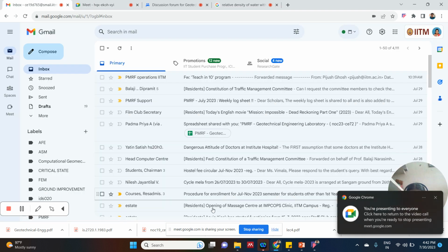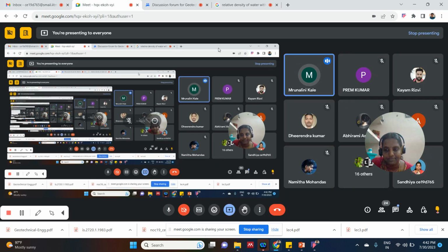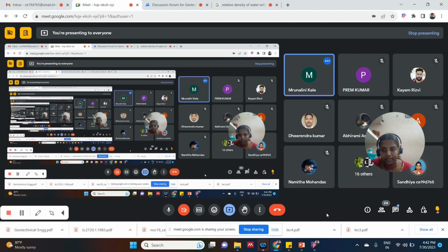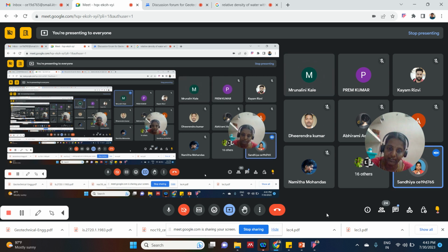Yes. Tare means the cup. The containers we sometimes call tare. In our weighing machine also we have a word as tare. In our weighing machine, tare means you make it zero. For example, I want to take some 50 grams of soil, I put a container or a tray on the weighing machine and I press tare, so it comes to zero. That is, the weight of the tray is not considered. So now I will take 50 grams. So tare, container are all the same.